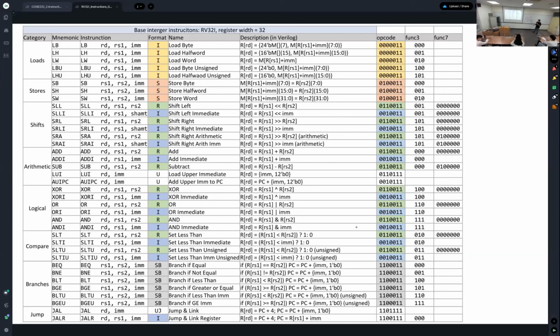It's the same. In order to access data from the register file, we require a register number, and for the store instruction, this register number becomes another source register, RS2. And in order to access the main memory, the store instruction also requires an address. To calculate the target address of the store instruction, we use the same form as this one.